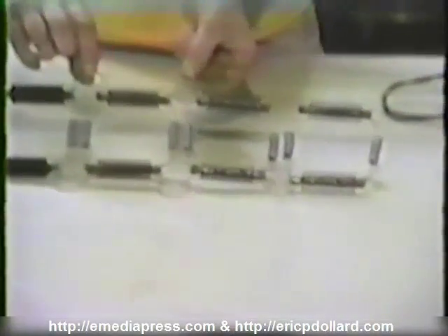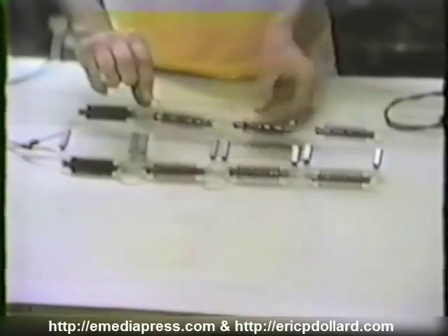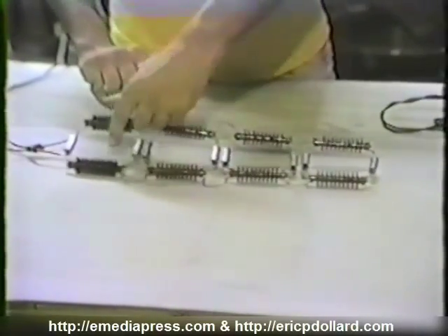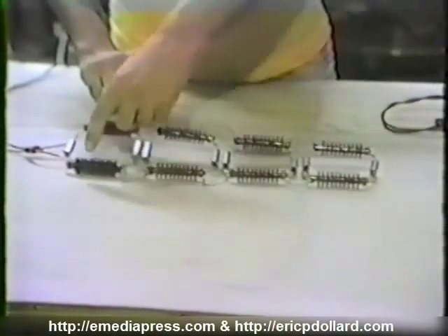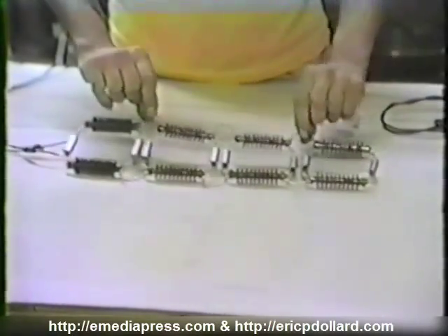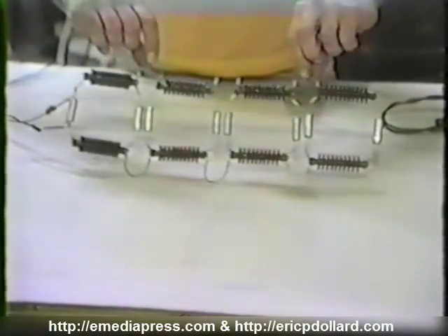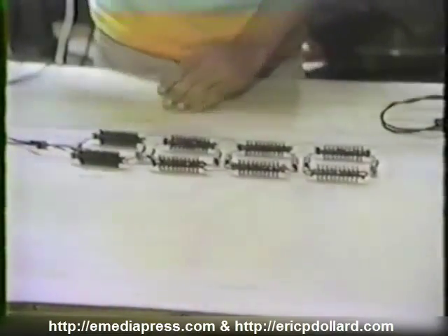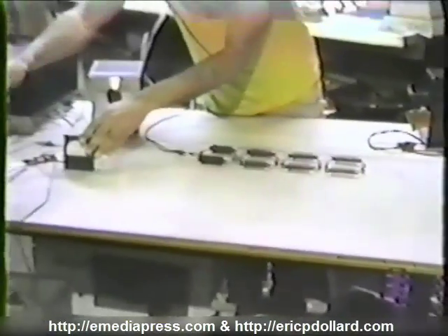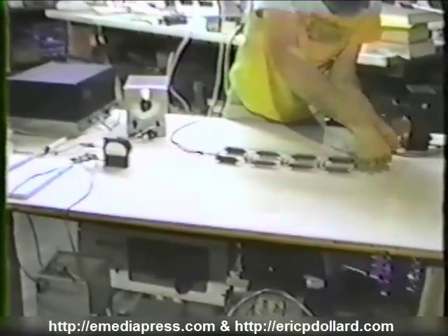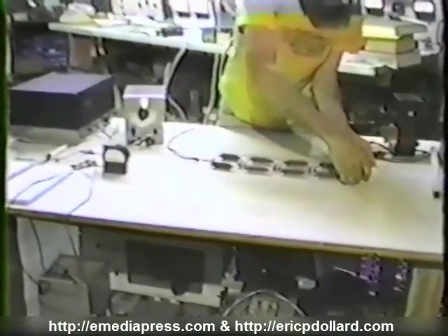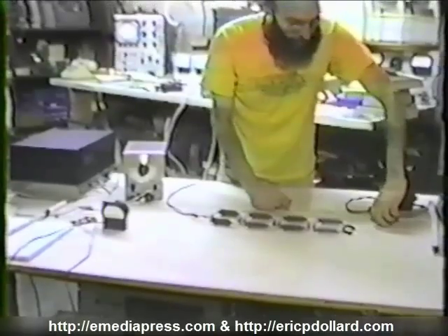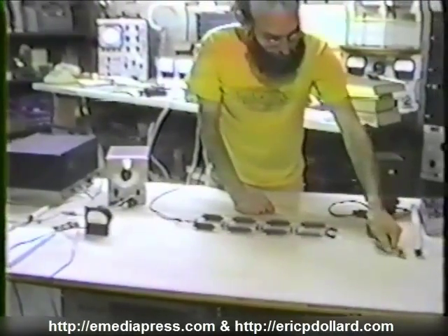So this is our analog of transverse electromagnetic propagation. You can see the capacitors are in shunt and the coils are in series as shown on the board. And it produces a definite geometric pattern. And of course we've got points where we can make measurement here. Now what we're going to do is determine the resonance, again by measuring the dielectric potential at the end. This time we're going to use the neon bulb rather than the voltmeter.